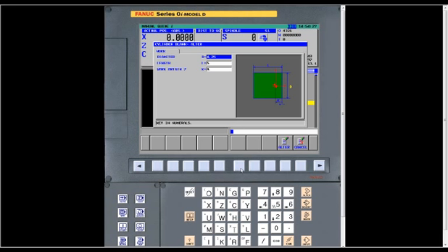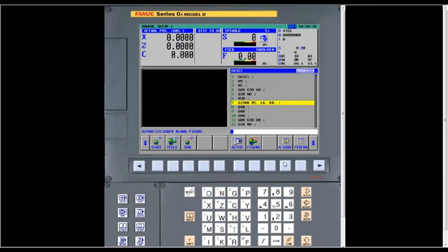Then you just change it, like I have 4 1/4 for the diameter. If I put 5.0, you can put that and say Alter, and see it change in the program. It's very simple. The mistake a lot of people make, Mark, is that it always defaults to the last blank figure that it had, and a lot of people don't actually put this in their program, so it's important. Number one, you put it in the program, and that's how you actually go in and change it. Okay.